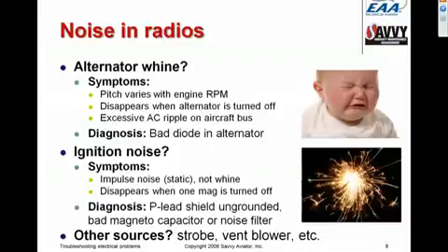But if a diode fails in the alternator, the output of the alternator will have a large AC ripple component, which I'll show you in a moment, and we hear that in our headsets and so on as a whine, which varies with engine RPM and goes away when we turn off the alternator.